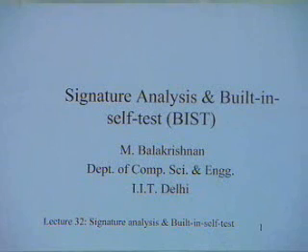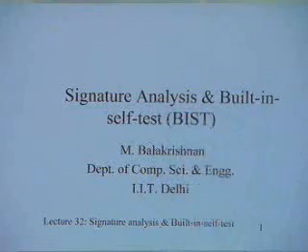So external testing. The built-in and signature analysis are coupled, because typically, of course, signature analysis can be used also in external testing, need not be only as a self-test. But typically for today's complex systems, when you are doing BIST, built-in self-test, you almost always use signature analysis. So it's sort of a one-way coupling, in the sense that signature analysis can also be used for external testing. But in today's talk, I am going to cover both of these.